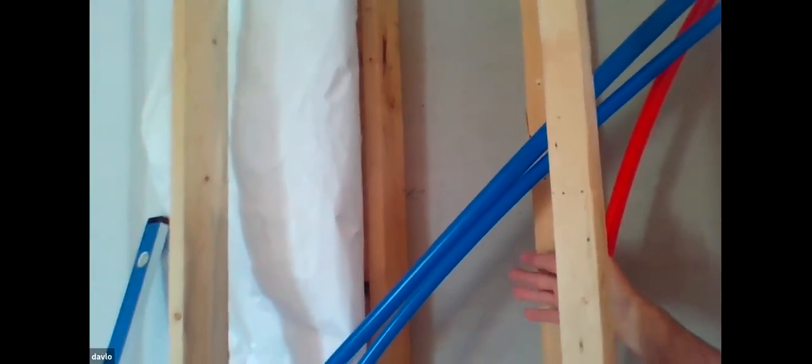But look at this over here. This wall right here has a 6-inch cavity in between. This is like building walls like this. So now you can run your pipes and all your ductwork through this wall, and you don't have to worry about screwing through the pipes. It just makes it a lot easier for plumbers. There are a lot of advantages to having a secondary wall in there for plumbing. Look at all the work the plumber has to do, how many holes he's got to drill, as opposed to no holes over here.